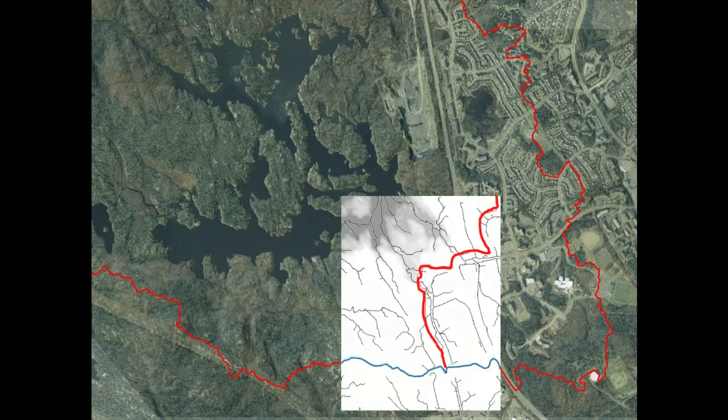You stick a rain gauge in the middle of your watershed, you see what the depth of rain collection is there, and then you map that out over the entire area of the watershed. Well, if you know that the natural watershed is 10 kilometers squared, then you can calculate a specific yield. You can relate that to runoff at your gauge endpoint, and then you've got a relationship between the two. But the problem is, if you've actually got this kind of thing going on, your natural watershed may not represent the true area of water collection that is actually being routed to the basin outlet.